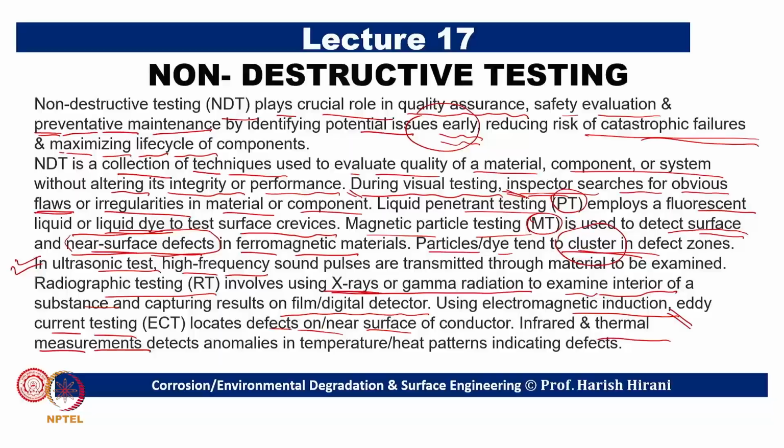It depends on what kind of sensor we are using and what sensitivity of the sensor we choose; that will be important. We also know that temperature follows some pattern, related to the thermal conductivity of the material. If the material has a crack or some discontinuity, naturally thermal conductivity will not be there, and the temperature will drop there. So we can look at that pattern of temperature or heat and figure out there is some discontinuity or flaw in this case.